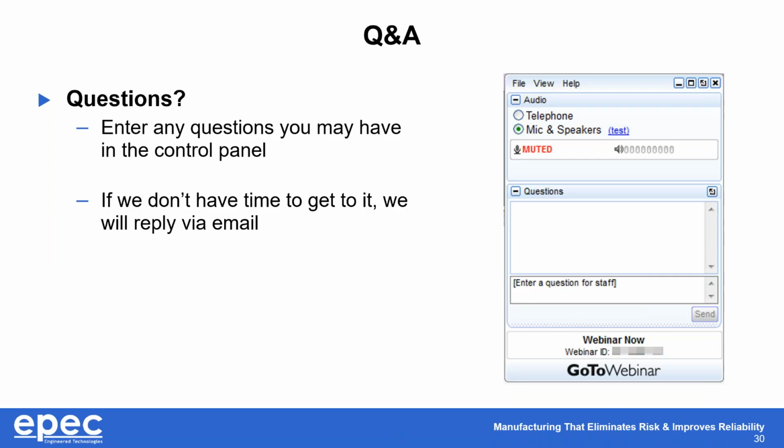My design calls for 85 ohm impedance. Do you have a stack up for that impedance? So I believe we do have an 85 ohm stack up. Generally, we will be able to supply stack ups for things like 50 ohm single, 75 ohm differential, 100 ohm differential. There are certain standard, quote unquote, impedances. However, some designs might require unusual ones that may end up going outside of those for whatever reason.